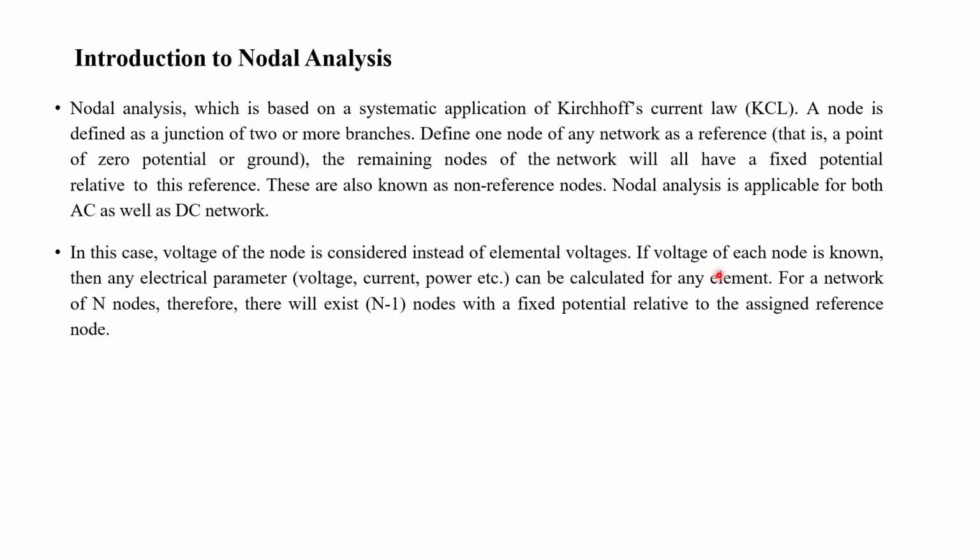Now, if the voltage at each node is known, then any electrical parameter in the given circuit, which may be a voltage across an element, a current through it, or power consumption by any element, can be easily calculated. For a circuit having n nodes, n-1 non-reference nodes exist. Nodal analysis is classified based on the following three cases.